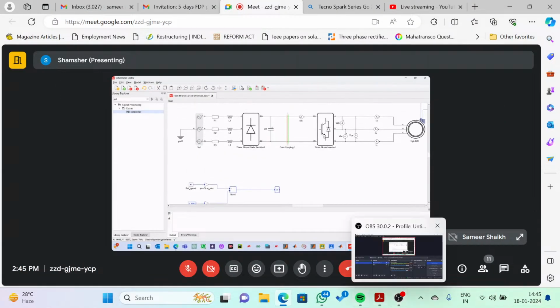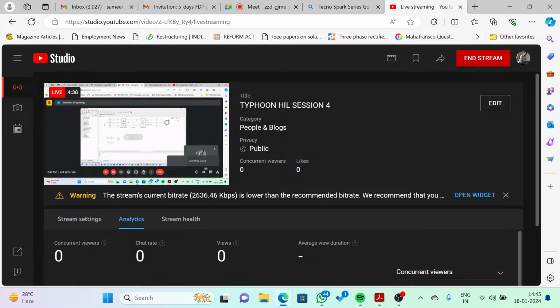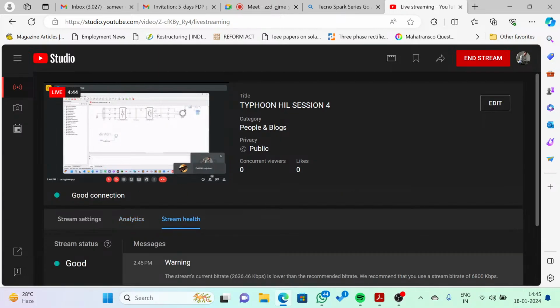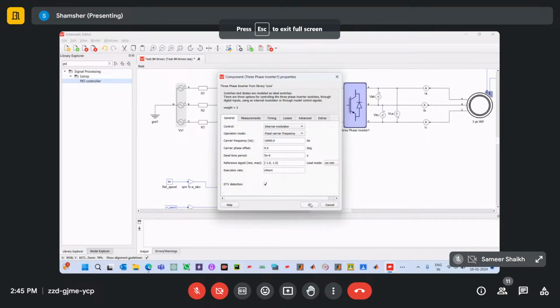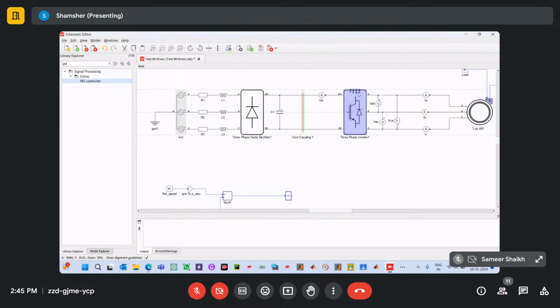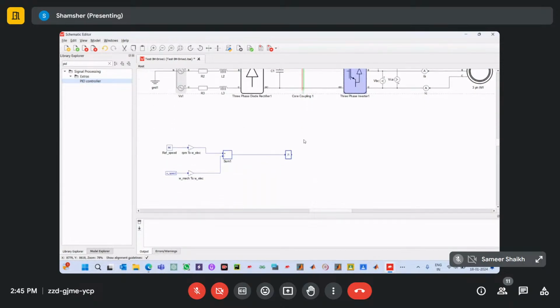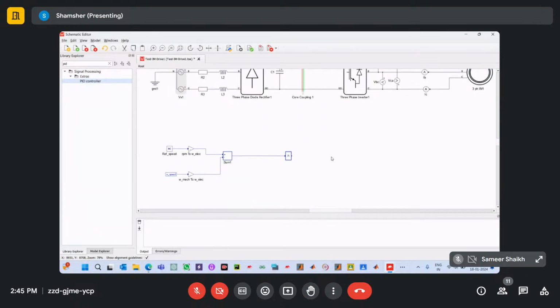So here is our inverter. This inverter can take different types of input. Here our aim is to take the internal modulator. It will generate an internal carrier signal of 10 kilohertz. So we just have to give three reference signals, you can see this INA, INB, INC. These three reference signals we have to generate here with the help of this signal. That information will go to this three-phase inverter, and the three-phase inverter will start working. So that is what we have to do here.